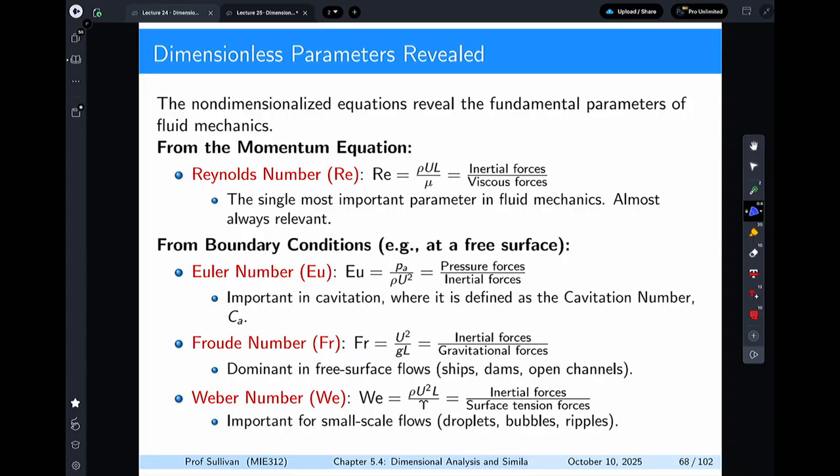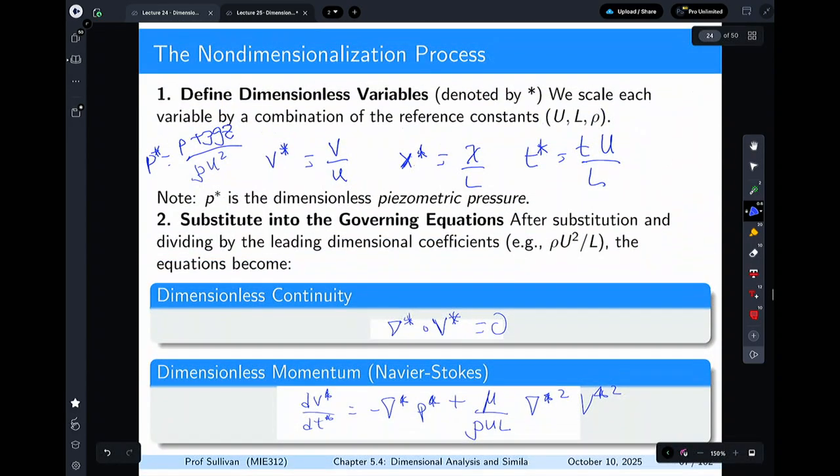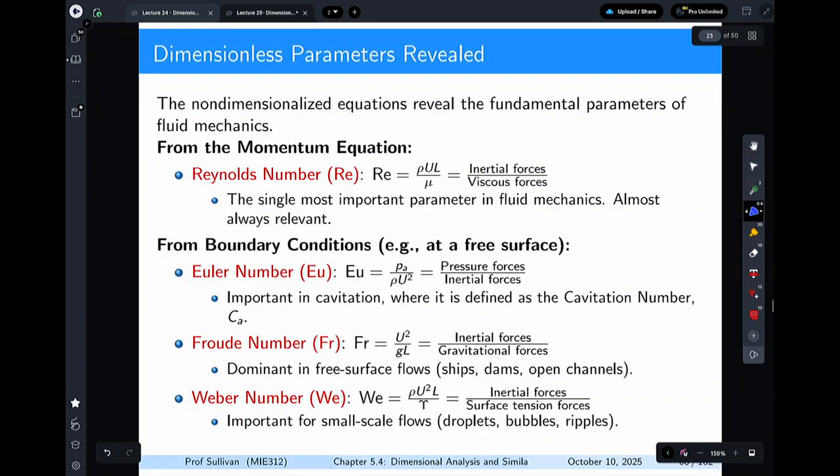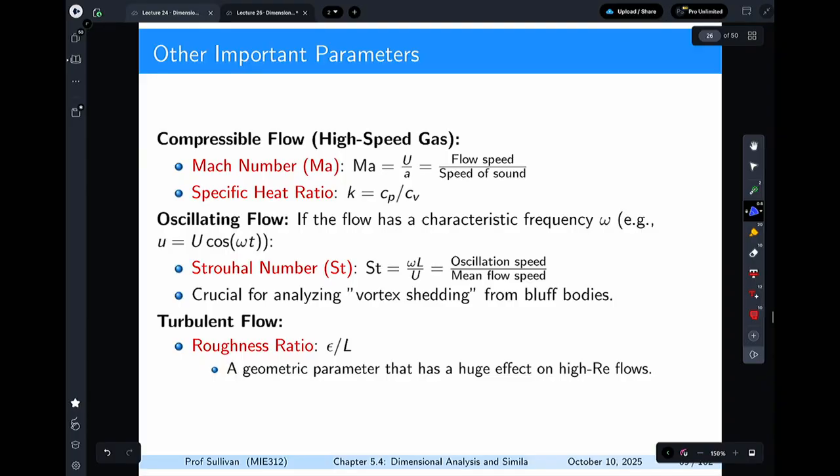One of the things that we do with this equation at the bottom is say, I can get rid of a lot of terms, for example viscosity, this last term, because it's associated with viscosity. If this is very high, very high Reynolds number is associated with potential flows, and you end up not doing it in this course, but in other courses.